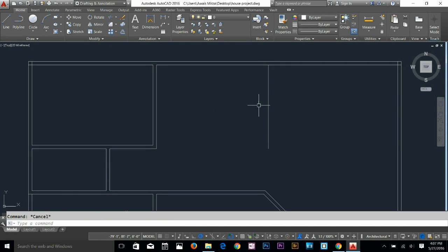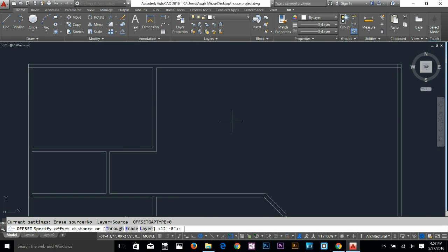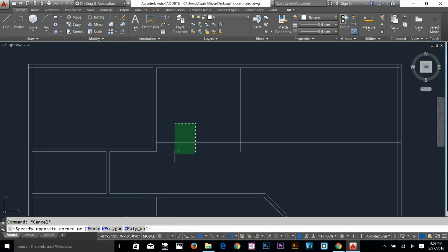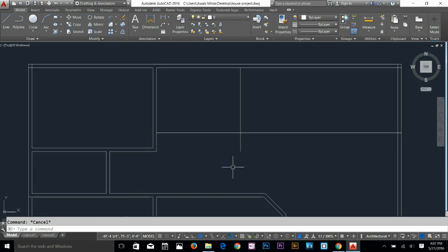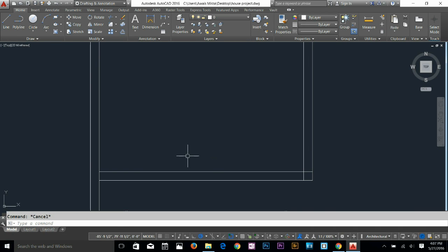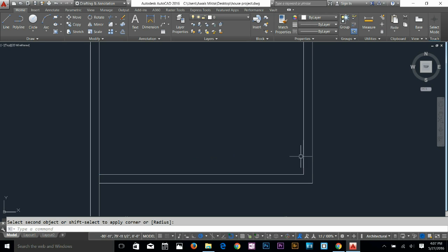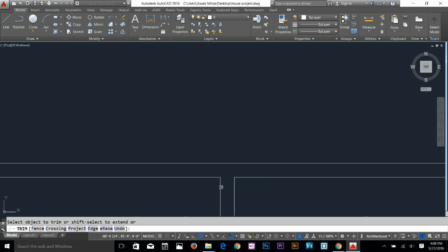So I'll give offset of, let's say, 9 feet. Okay, and then I want to give offset of, let's say, 8 feet. This is, move this a little bit up for like 1 feet, so you can use your chamfer command. Alright, so well, I'm gonna offset about 4.5 inch worth of walls up, left, and then use your fence selection in a trim command by using F while you are in trim command. So fillet command, get rid of this line and just trim off these lines, right?